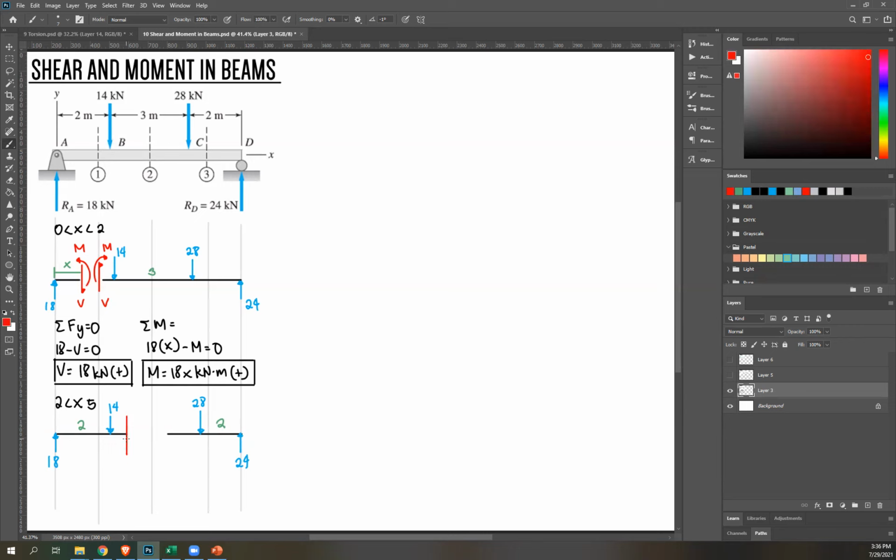And then shear force. We're going to assume again the direction of shear force. I'm going to guess it's downward once more. Why? Because this is 18, this is 14. I need another downward force to create equilibrium. That's why I made the shear reaction downward. Next for moment. 18 creates a clockwise moment, 14 counterclockwise, and 18 is larger. So I need another counterclockwise moment to counter that. And then on the connecting member, just do the opposite. So this is V, and then this is your M.